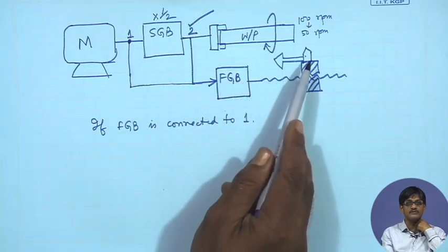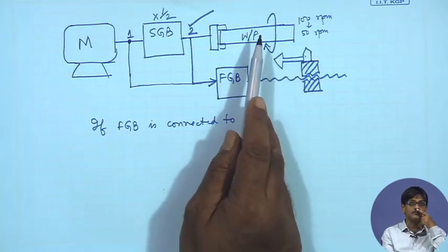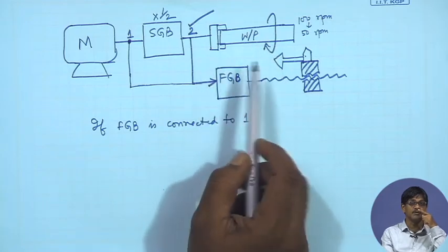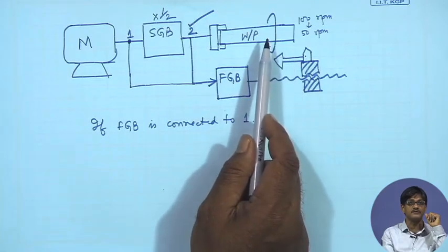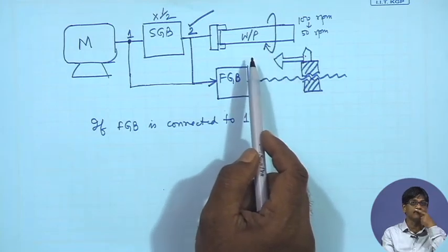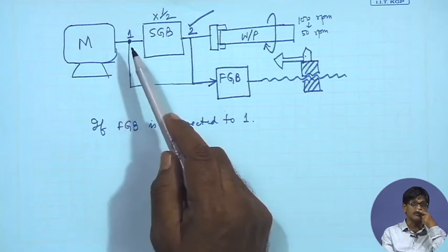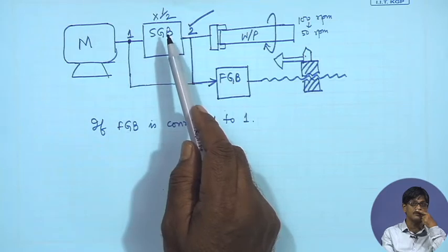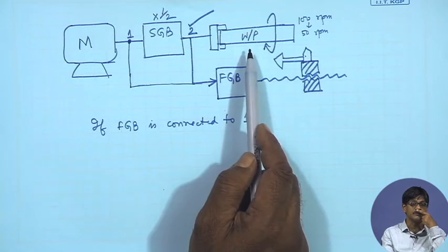And this moves at the same speed, and hence the relationship of movement gets disturbed and you will be cutting a different thread, because thread is defined by movement of this one per rotation of the workpiece. The workpiece is moving slower now and you will cut a smaller pitch thread, half the pitch will be cut now. So, it is a problem if you connect it here, and if you are doing something to the speed gearbox, be very alert, because the thread which you are cutting will be changed.